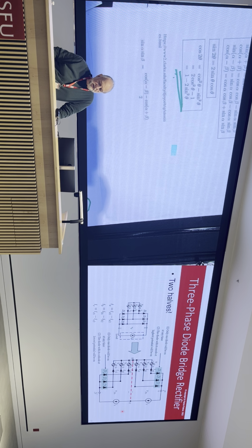How else are we going to think about this? It's actually quite useful because you've got 6 potential current paths. Because of that, it's quite useful to think about the bridge in 2 halves. So we'll just repeat these things down here. They're voltage sources, so we can pretend that we've got 2 of them, and we've separated out the positive half of the bridge and the negative half of the bridge. So that's quite nifty. Why can I do that? There's not a connection across here.